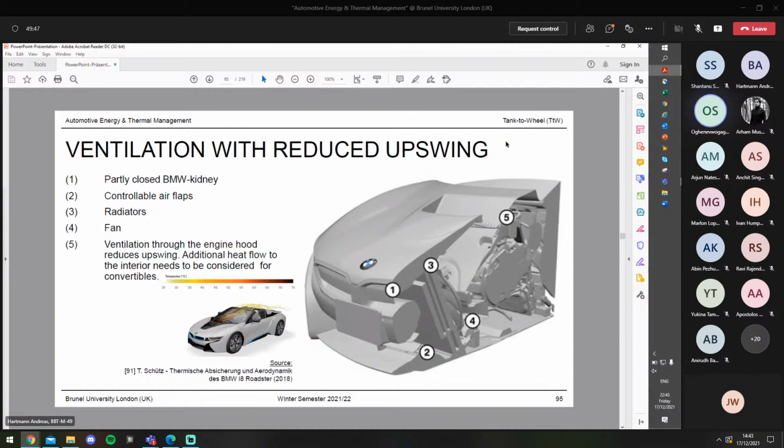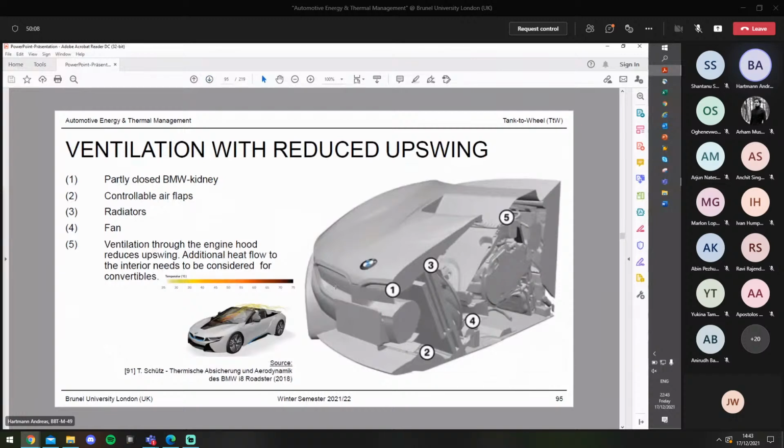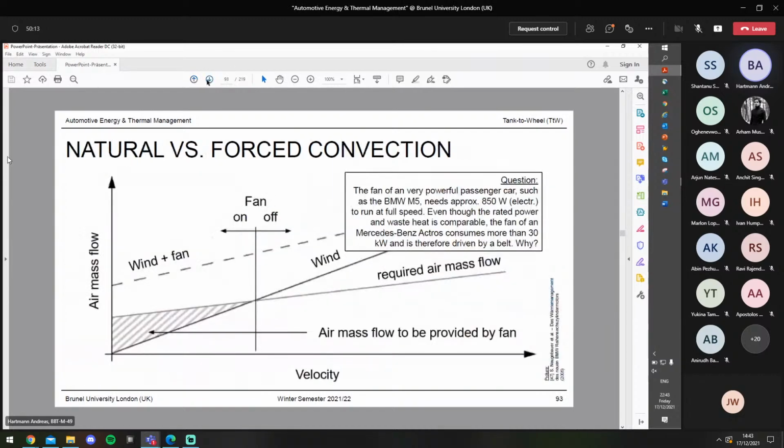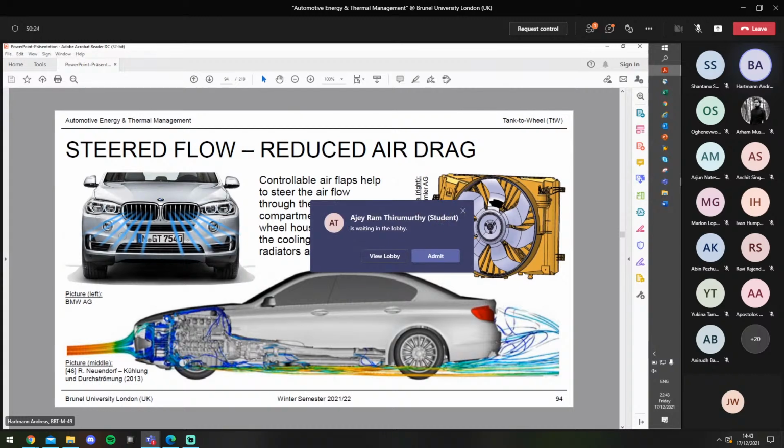Could it be for increased grip for the tires? Exactly. This is the reason, to create more downforce. Maybe not so much reducing the drag, but if the air flows through the engine compartment and then leaves again on the underfloor, you might even reduce the downforce by doing so.